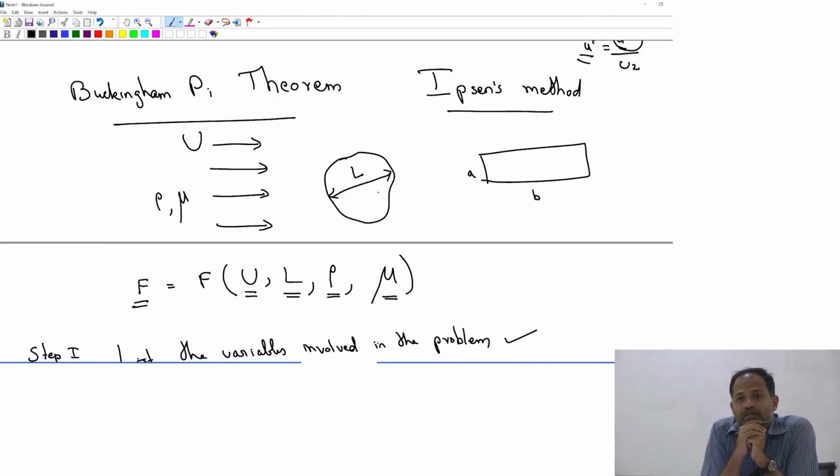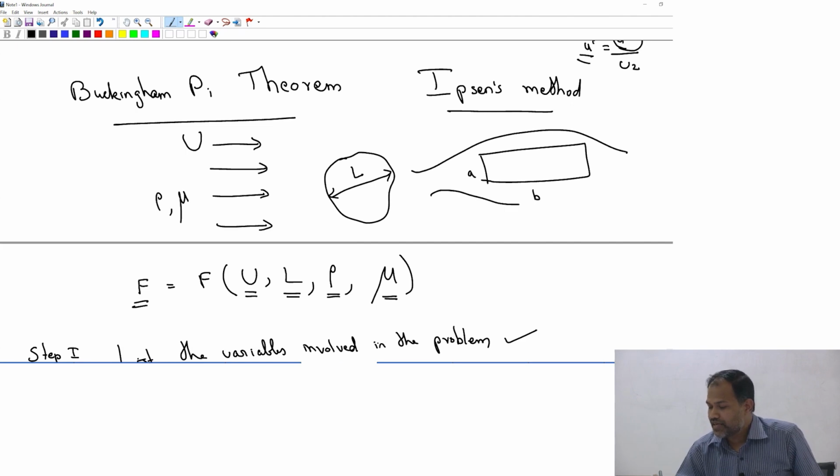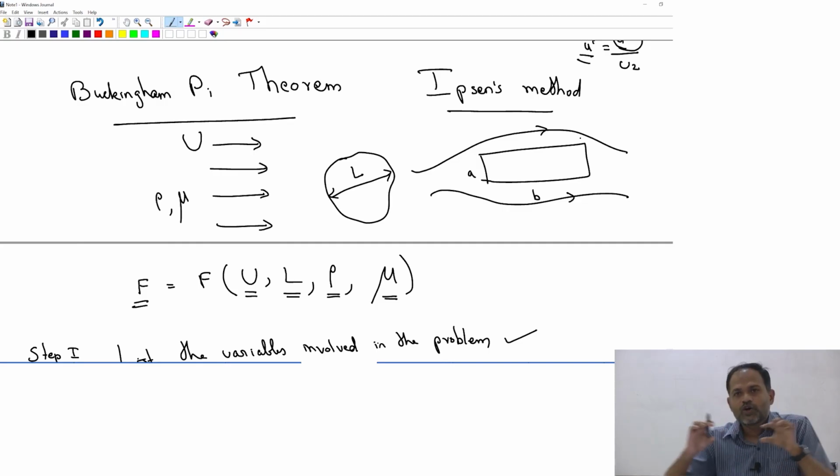How do you know B does not have any effect? See, fluid is going to go like that, right? So the regions of B, it's coming in contact a lot. There you are applying the no-slip boundary condition. The fluid is indeed going to slow down, right? Whether it's a smaller one or a longer one, the fluid will slow down to different extents.